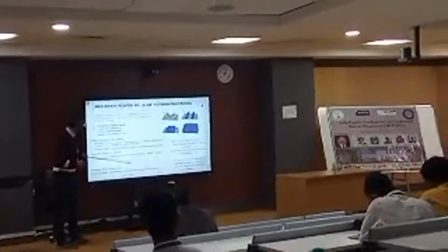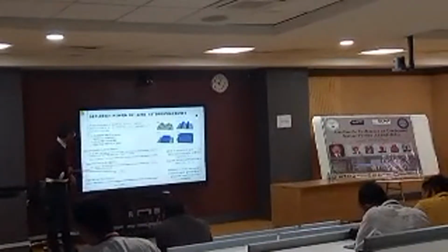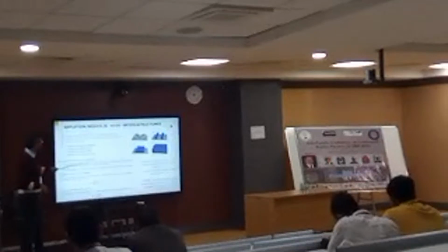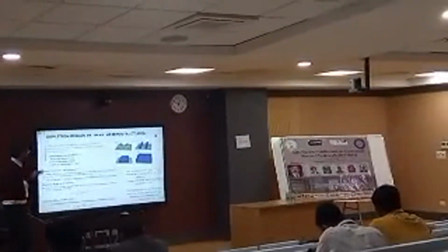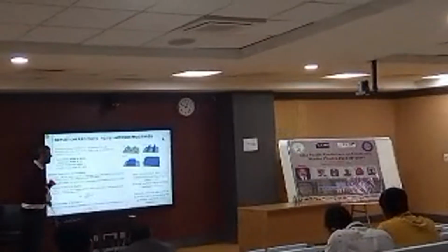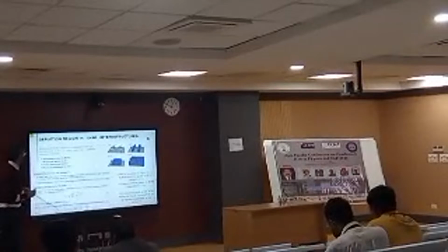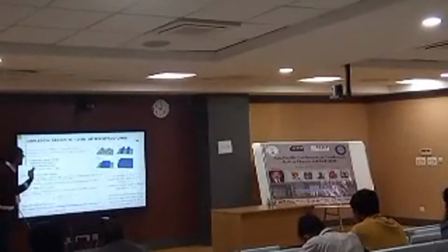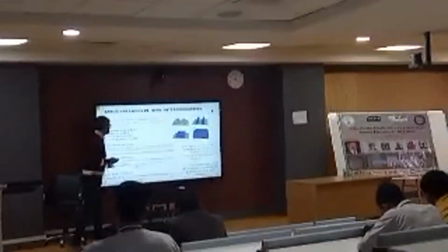So this is the depletion region expression for 1D tellurene and 2D MoS2, and you can calculate from the numbers that it's of the order of 6 nanometers. From a very basic calculation without doing anything from the materials perspective. And the built-in potential is 1.1 volt, and it's an extremely localized depletion region,